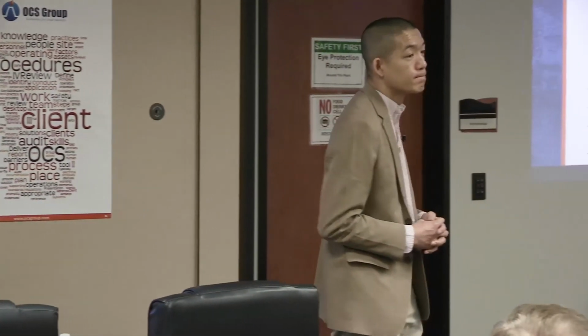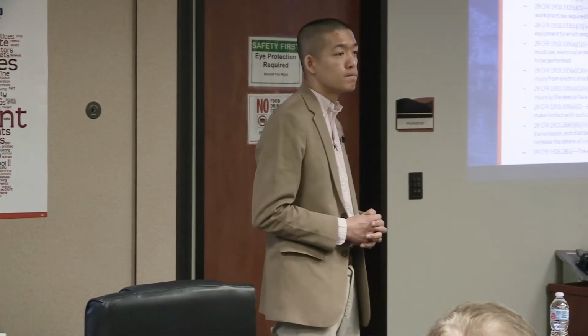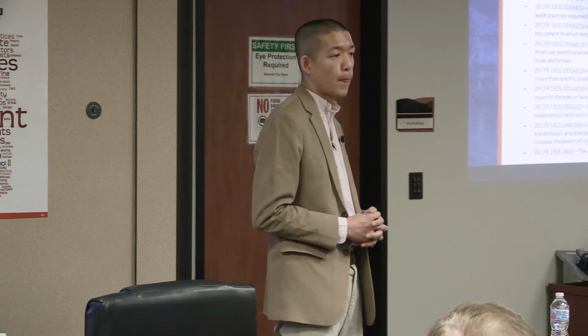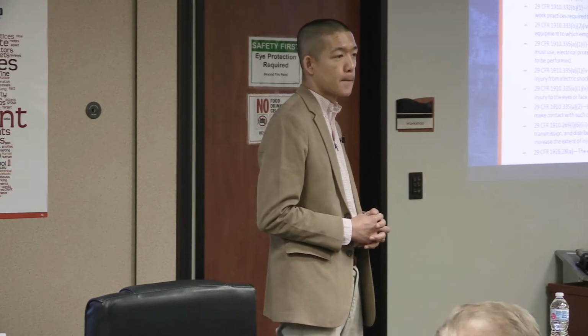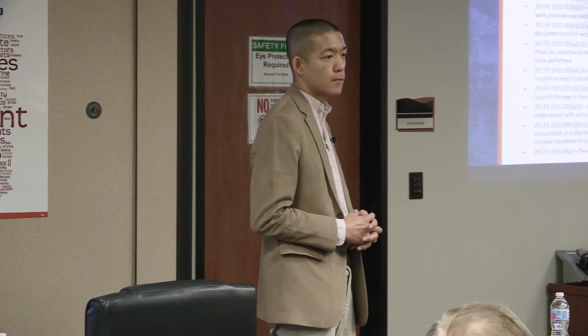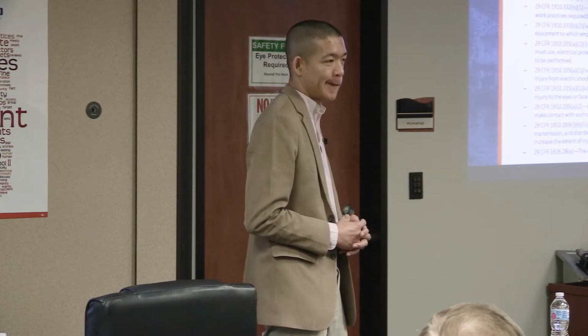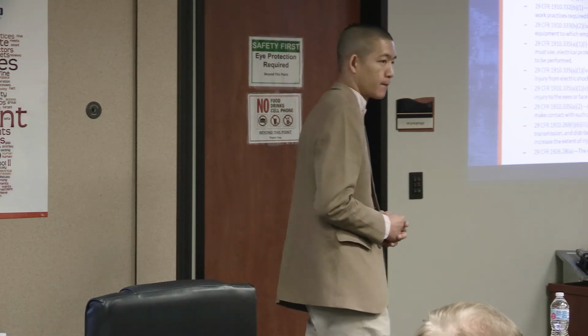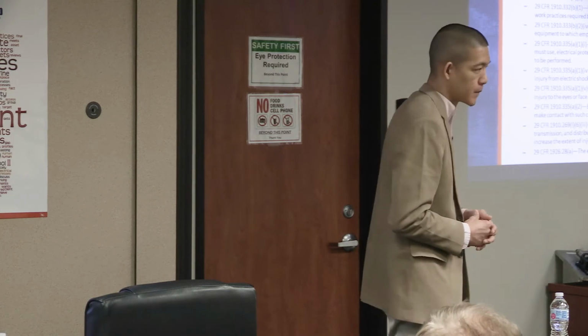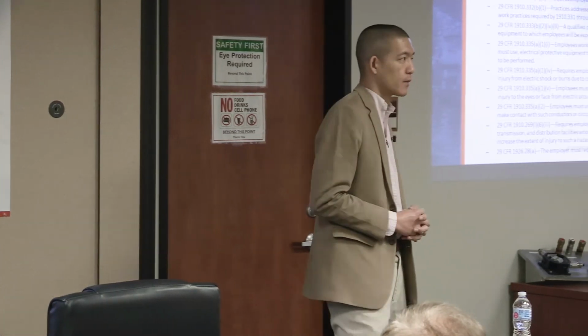When you do, I'm assuming it's a new facility or a new piece of gear, something you're doing an arc flash analysis, risk analysis. At what point, with the exception of doing a major overhaul, does a management of change require you to redo it for either that piece of gear or the whole place? Every 5 years at a minimum.